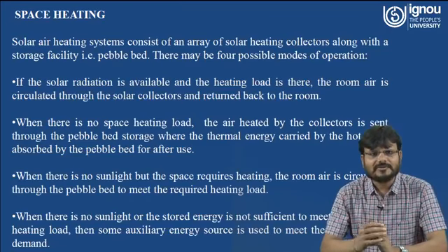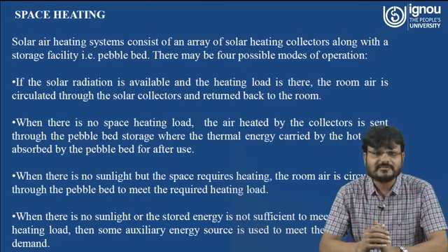And how it can be used for space heating, we can understand here. A solar air heating system consists of an array of solar air heating collectors along with a storage facility, that is a pebble bed. There may be 4 possible modes of operation.